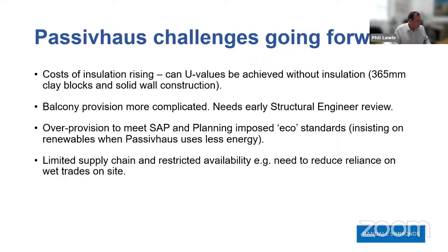There are some challenges that we've come up against. Cost of insulation has been rising significantly for some time. We are building certain units without any insulation using poroformed block and a monolithic construction, but we'll go back to the point about, at the moment, you can't get a warranty cover for those items.